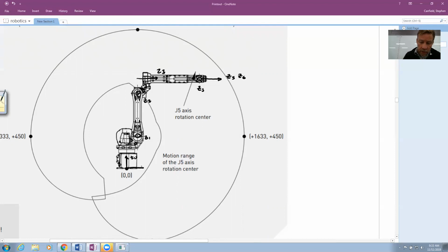To define my X's, I'm going to put my X0 here. I've got Z0 going up, cross with Z1 coming out at me, so that I'll put X1 out here, that intersects both. Z1 cross Z2, they're parallel, so I can put my X2 up here. Z2 crossed with Z3 puts my X3 going up. So now notice, kind of like before, I've got all these orthogonal guys, but now everybody's showing up in the positive direction just because of the direction I assigned the Z's.